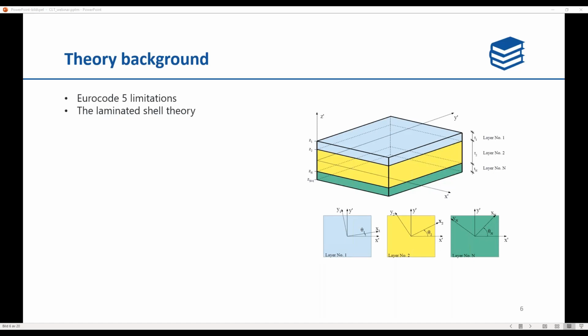The main advantage of this method is that with a slightly increased calculation time for the element stiffness matrix using a homogenization procedure, the same number of equations remains in the final structural equation system, regardless of the number of layers. Another advantage is that this method allows for arbitrary geometries of shell regions and boundary conditions with additional solid shell and bar elements, because this way the degrees of freedom are compatible with each other. In addition to this, we also needed a new finite element formulation. The tricky part of that is the coupling effect between the bending and the membrane behavior. We'll get back to these things later when we look at the stiffness matrix.